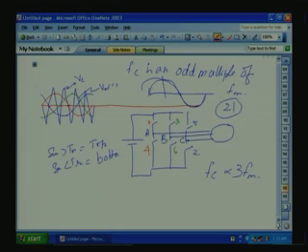What is the advantage? For motor drive applications, as I told in the previous class, we are connecting like this. The neutral is not connected anywhere. So, in the PWM waveform, VAN, VBN, if the triplen voltage is there, triplen current will not flow because the neutral is removed.